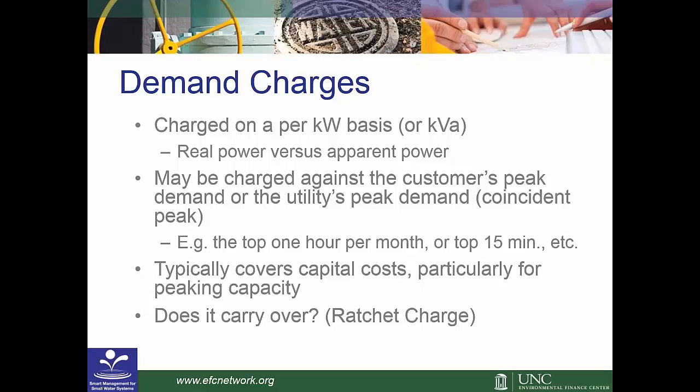And that gets to the question of how you manage your peak for your water system, if you have any leeway in how you do that. Another thing to be aware of with demand charges is that with the energy, the kilowatt hours, you're just charged this month for what you use, and that's the end of it. And next month you'll be charged for what you use next month, and that's the end of it.